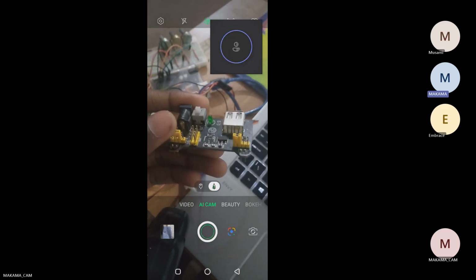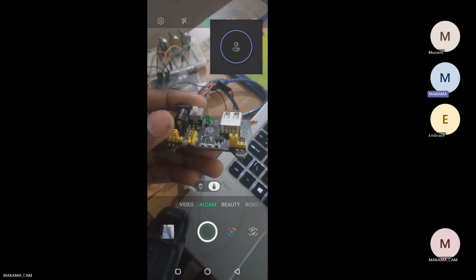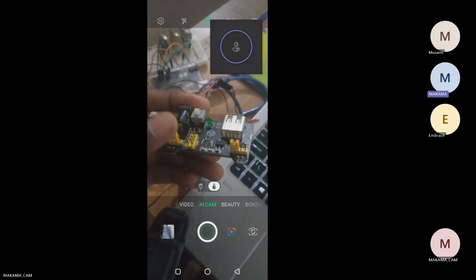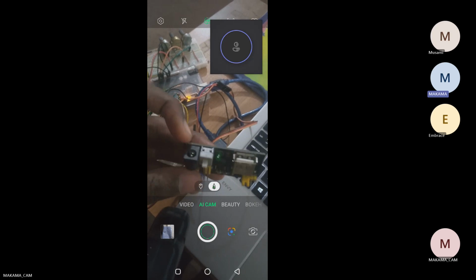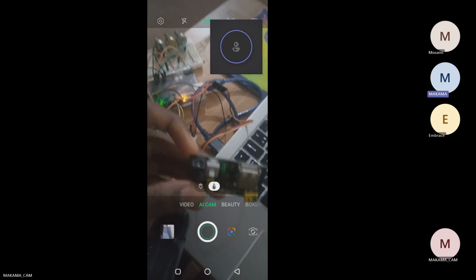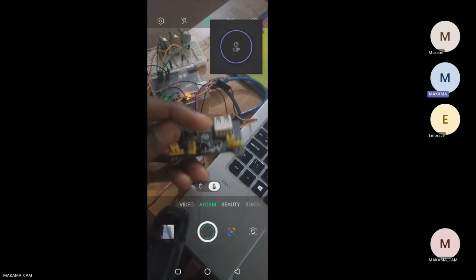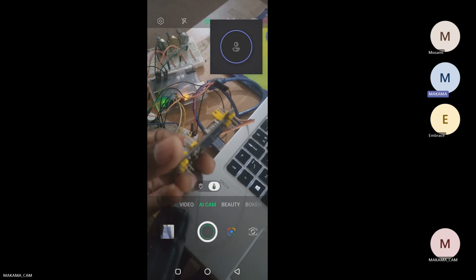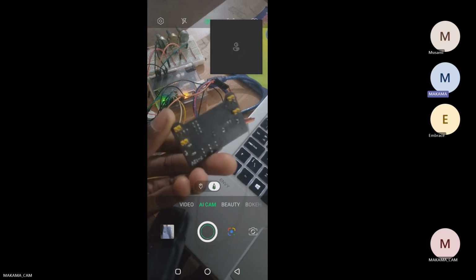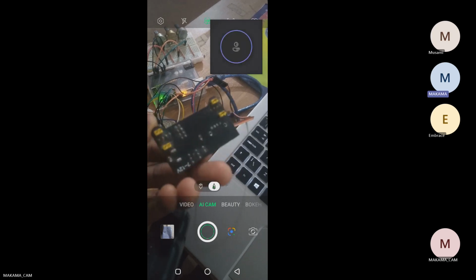You can search for the schematic diagram for it online. It's a very simple diagram. You just need a voltage regulator and stuff, so that once you power it through this power jack, which is 9 volts, it goes through the regulator and is regulated to 5 volts, and you have pins. It's laggy, right? You can see it, right?